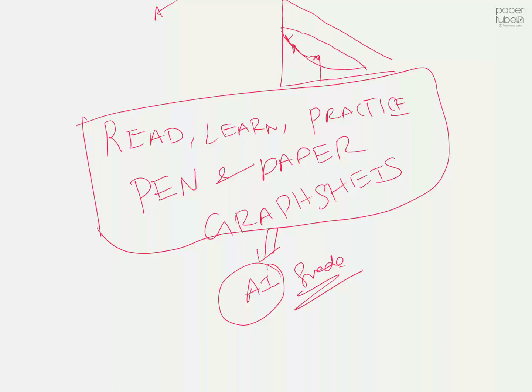Imagine you are purifying paracetamol, which everybody knows about. If you are purifying paracetamol using isopropanol in a 20,000 liter reactor, we cannot dispose of all 20,000 liters of solvent once you finish your crystallization. So you should find some ways to recover your solvent, and normally for that we will go for some unit operations. One that comes to my mind is distillation. These are the things you should have some idea about, and that's why we are studying different unit operations in this module. So that's one good reason you are learning them.